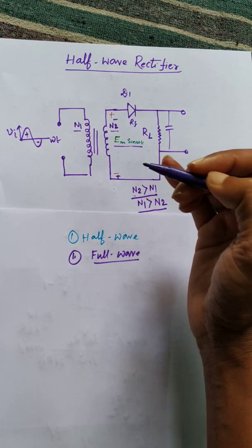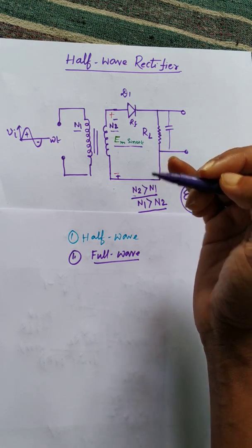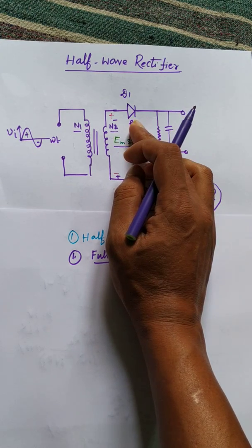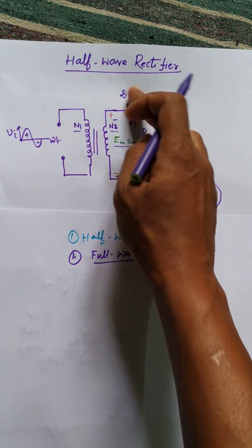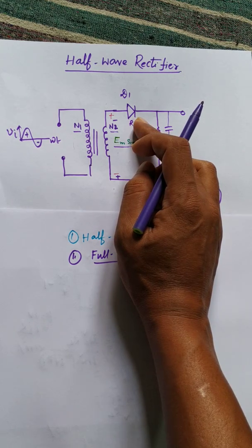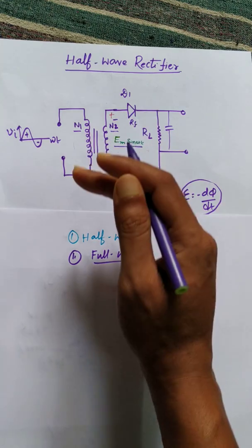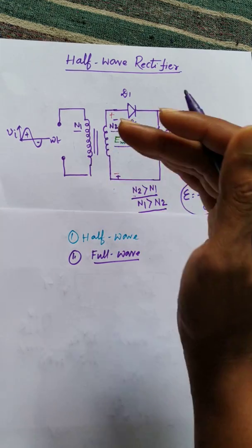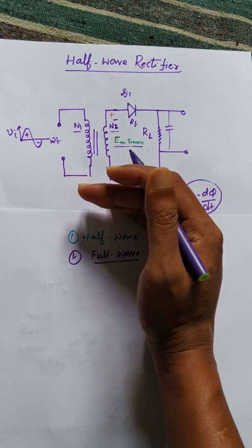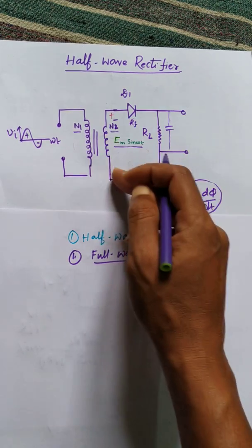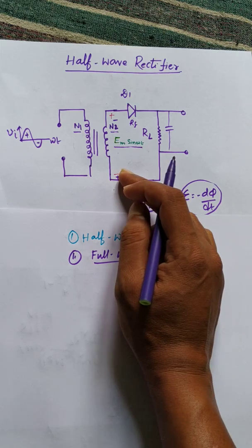But in the reverse bias condition, the PN junction diode offers very high resistance, so it behaves as an open circuit. Thus, the PN junction diode conducts electricity only in one direction, and this character is used for rectification, and this is the working principle of the rectifier also.